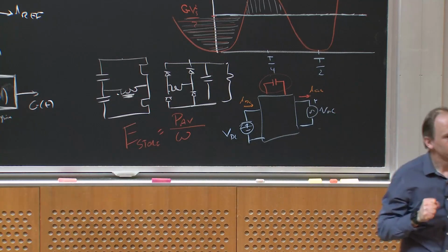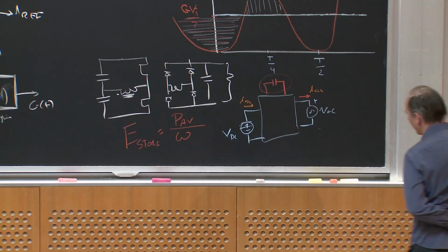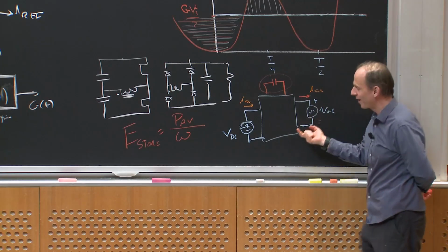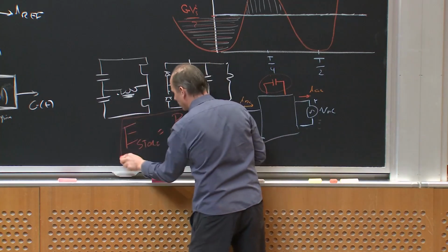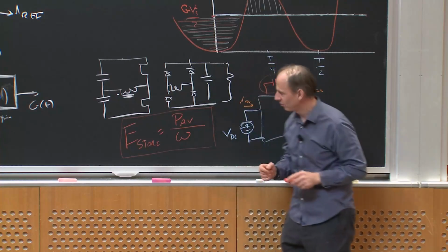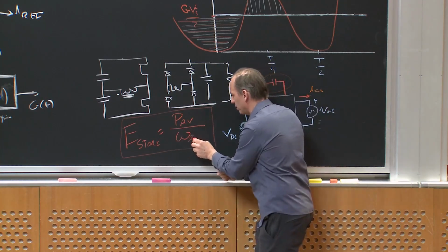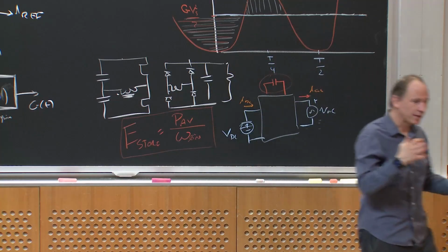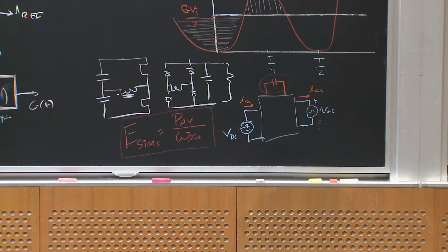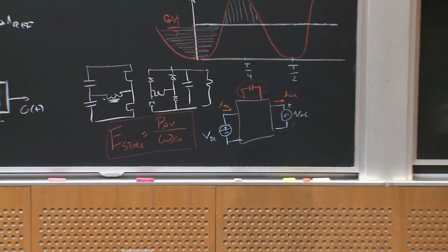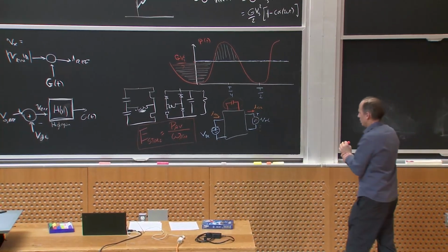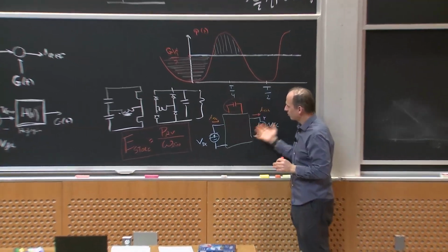So, when we said I want to increase the switching frequency of my converter to make the components smaller, that's all well and good, but if I'm delivering energy to the line at unity power factor, I need to store a certain amount of energy inside my converter anyways, and that's related to the line frequency. Okay, and that's going to set a minimum size on the capacitors or inductors or whatever I use. Most people use capacitors because they have better energy density, at least at small scales, like the single-phase line scales, okay? So any scheme you're going to come up with, you're going to have to do this.